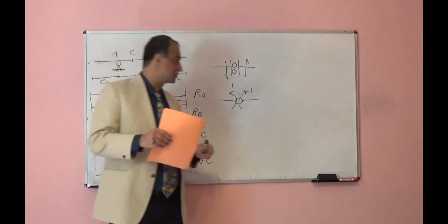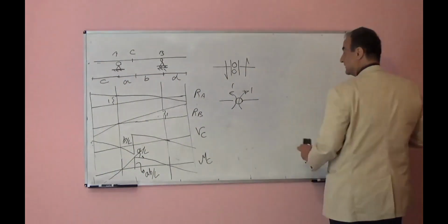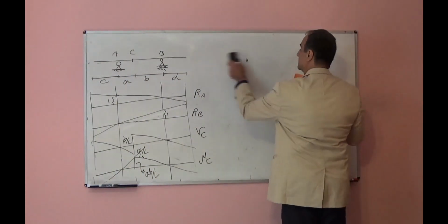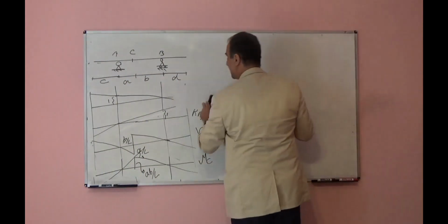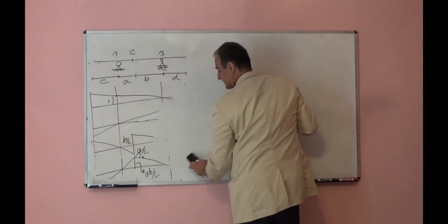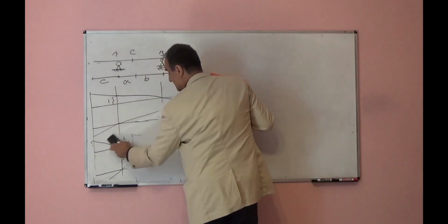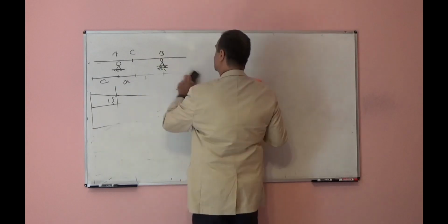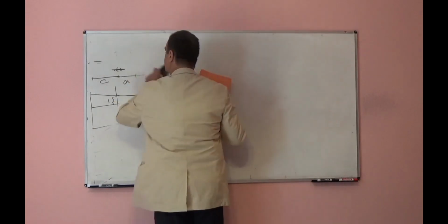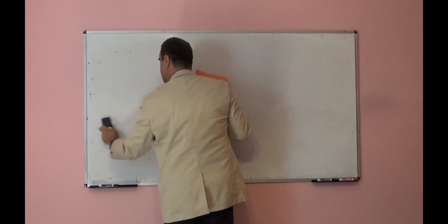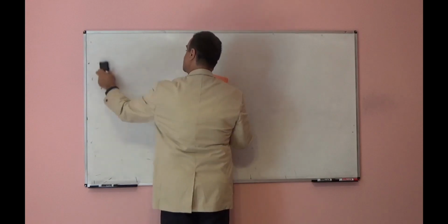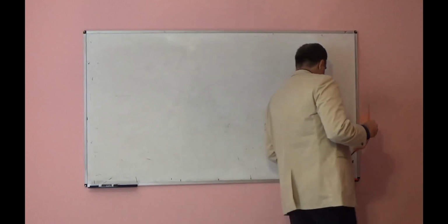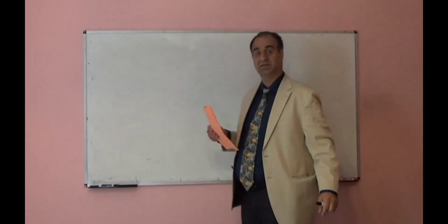Okay, in order to find the magnitude of reaction or shear force or bending moment, if our traveling load magnitude is not 1, I explain, if it is P, we will multiply P times the height underneath of that.